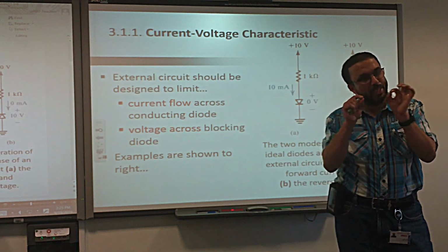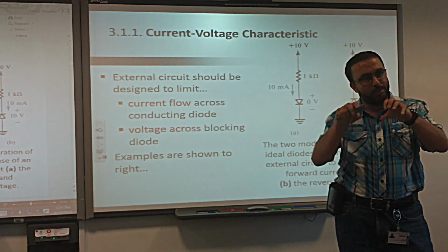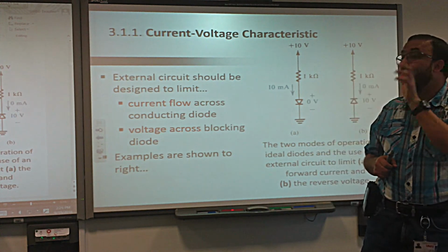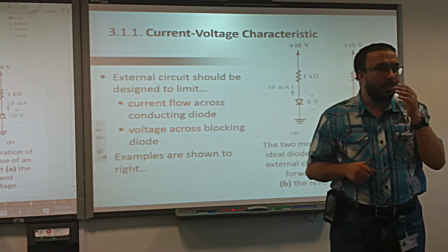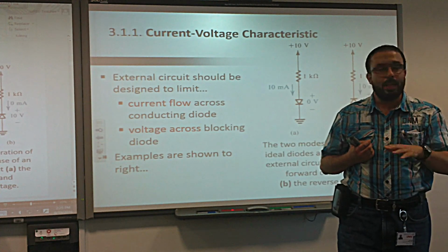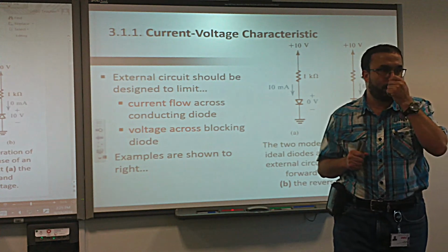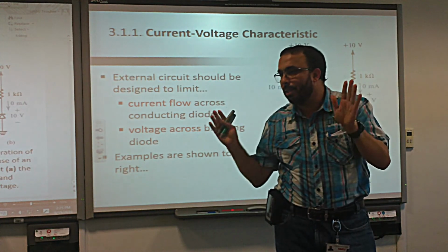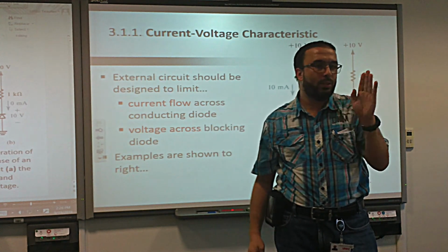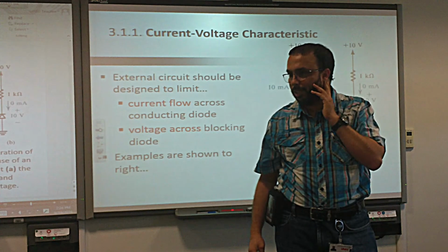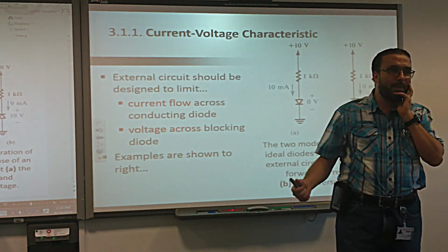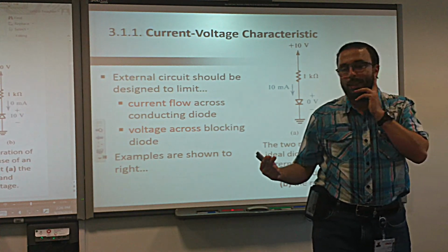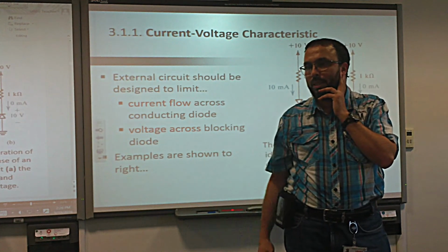It will burn if the wire is thin, right? Yes. Now if it is thick, strong, what will happen? The battery will be damaged. If it is a lithium battery, maybe it will burst. It will explode. If it is a normal battery, it will deplete, meaning all the charge will disappear. Do you understand? So never short circuit a battery, because you will damage your battery, you put yourself maybe at risk, and you will lose the power of the battery almost immediately.